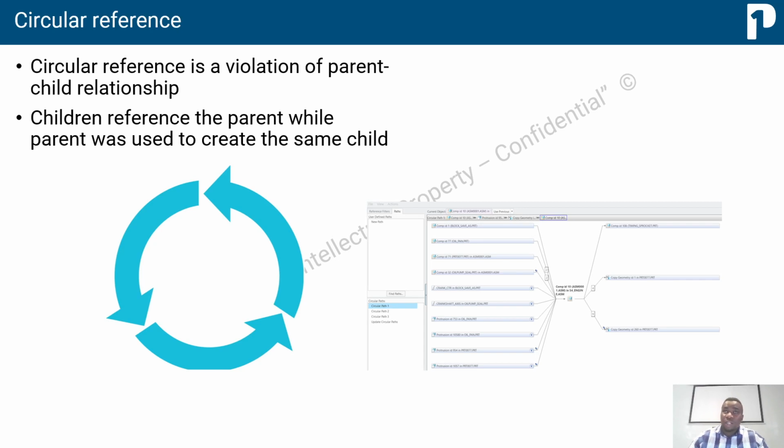Then I edit the definition of the plate with the holes, and I say, use those holes that were created referencing the boss to constrain on the parent or on the other plate. Now it creates a cycle, a circular reference, and it's going to give you some problems. So this is something worth looking into when you actually face it right away.